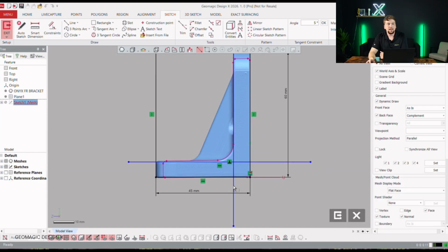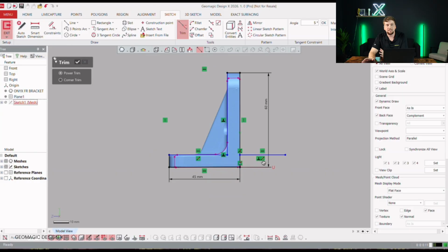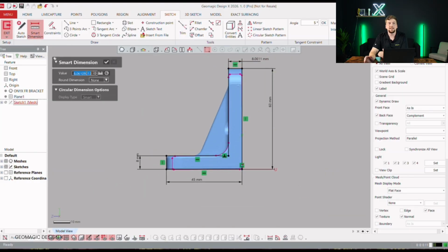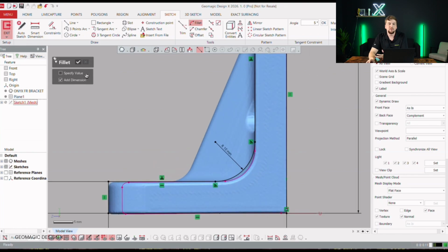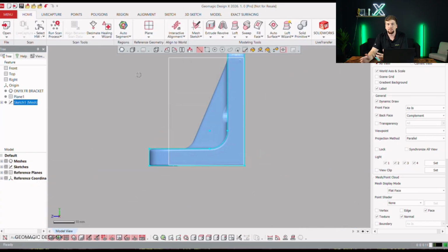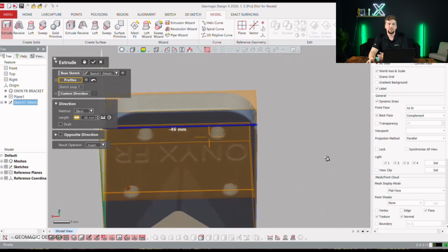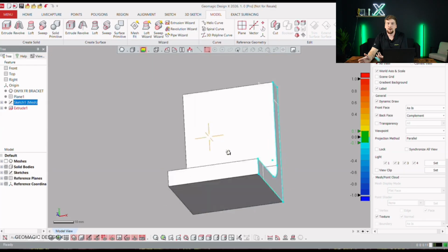As you can see here, I'm not specifically using those pink mesh sketches as my overall dimensions. I'm using them as references, and then I'm dimensioning my sketch around them to get my real world practice. Because I want this part to have overall controlled dimensions, such as, for me, I like whole numbers or half numbers like 40.5 or 40 or 41. I'm not looking to have that 43.3333 millimeter part. That is not the intended use for this piece of bracket here.